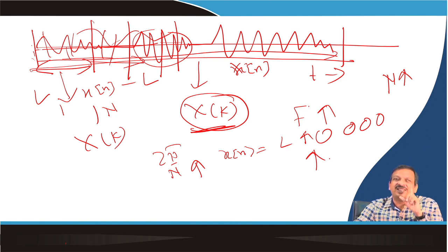Okay. So, that is that kind of things. So, use this in a practical scenario. I may ask you, suppose I have a signal, sampling frequency is given, I want to compute the DFT length of this, what should be the frequency resolution? What should be the amount of signal I have to take? What if my filter frequency response is this, what is the length of the convolution? What is the minimum length of the DFT I should take?